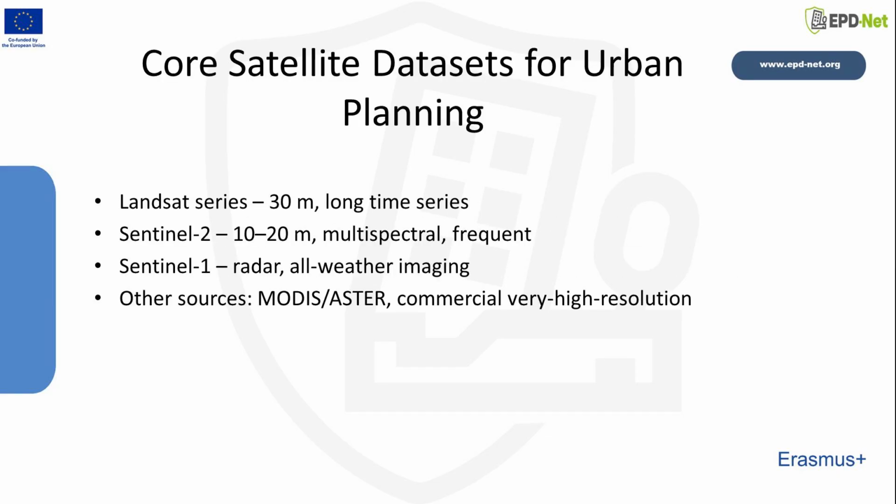Here we introduce the satellite missions that form the backbone of many urban resilience analyses. The Landsat series is highlighted for its multi-decadal archive at 30 meters spatial resolution, which is extremely valuable for detecting long-term urban expansion, loss of green space, and trends in land surface temperature.